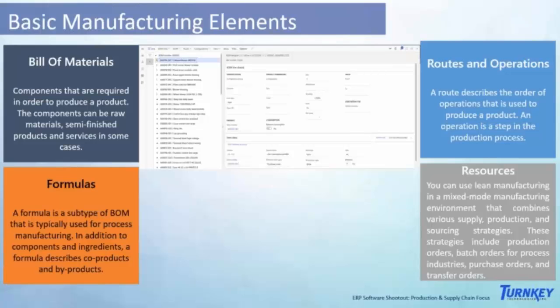So a bill of materials doesn't need to be something that is consumed, or something that is stocked. We can have bill of materials lines that are type vendor, which means it's a subcontractor. We can have part of the bill of materials be a phantom, which means we need it in my design because it's part of my structure, but I don't need to stock that part, because it's just a sub-assembly of two pieces that takes 1 or 10 seconds to produce. I don't want to generate a production order for that. I just want to consume whatever is underneath that phantom. So that is another option.